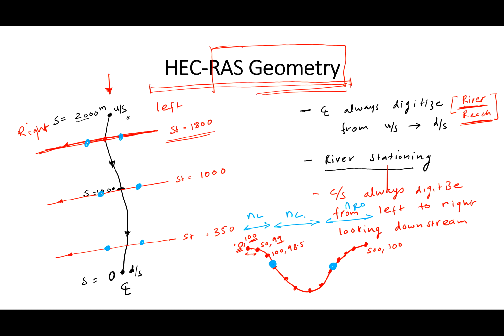The other piece of information you need is the distance between individual cross sections along the right over bank. Remember, we looked at LROB. This is LLOB, and this is LC. Now, as I mentioned earlier, if the channel is straight, LLOB, LC, and LROB are more or less the same, which is what you see here.